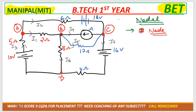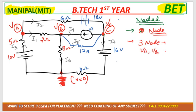Mostly the bottom node, we will do grounding, and at ground the voltage is equal to 0. So at this particular point the potential is VA, at this point VB, at this point VC. So in this case we'll have three nodes. Three nodes means we'll have three variables VA, VB, VC, and with three variables we'll have three equations. Any doubt up to here?